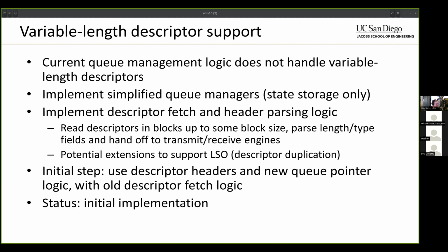I guess I didn't mention that earlier in terms of the board support, but I've actually overhauled 2 different board designs to support 25 gig that didn't previously support it. So the Stratix 10 MX and also the VCU108. So you can now run 25 gigabits per second on UltraScale, in addition to UltraScale Plus, which was already supported, and on the Stratix 10 MX. And both of those required quite a bit of work to get timing closure with the PTP CDC components and with the Ethernet MAC. So I've been doing quite a bit of work on the timing closure side just to get that.